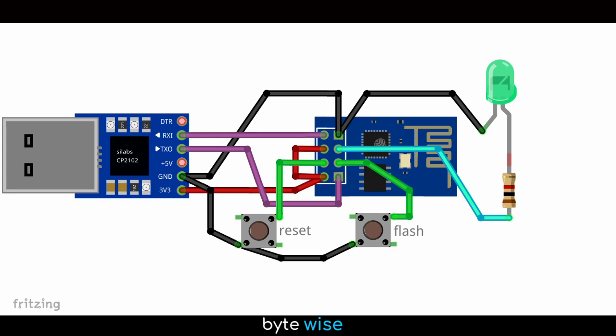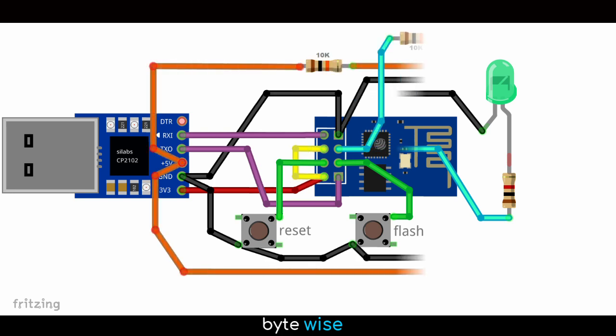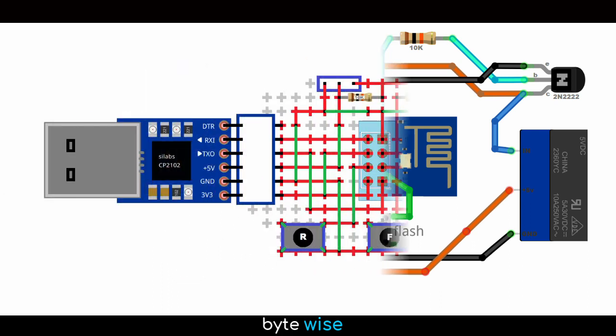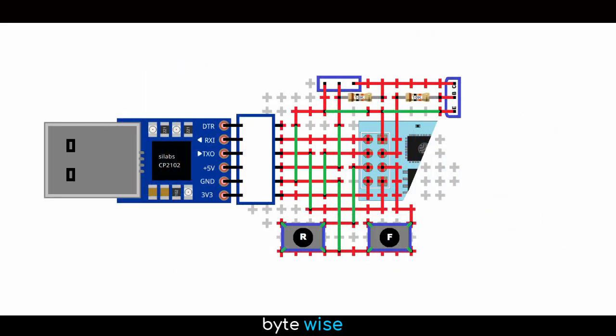For completeness though, we'll show the entire circuit, adding a transistor and resistors to invert the output of the ESP8266 and convert it to 5 volts before feeding it to a relay module. These relay modules vary. They usually have a built-in transistor driver and sometimes incorporate an opto isolator. So this is our complete circuit. Next, we'll put it together on a piece of general purpose perforated circuit board. This will be the design that we're working to.